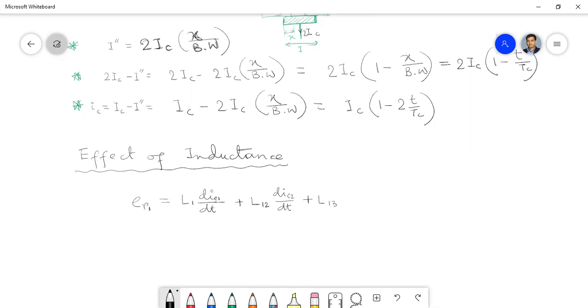So this is how we can write this. This can be a series because we don't know how many coils are going under commutation. If coils are going under commutation, then we can write this expression like this. Any doubt? This is the reactance voltage induced or developed in the coil going under commutation. This is called reactance voltage. Do you have any doubt? You can point out.